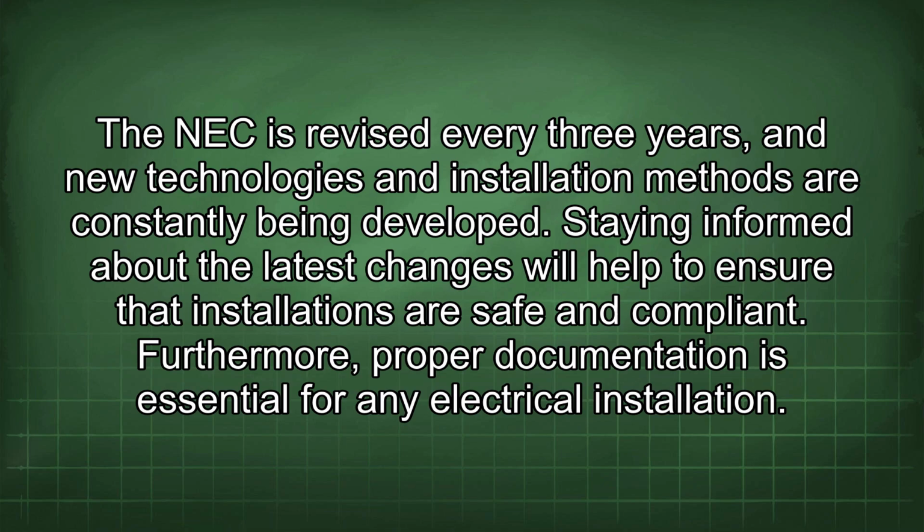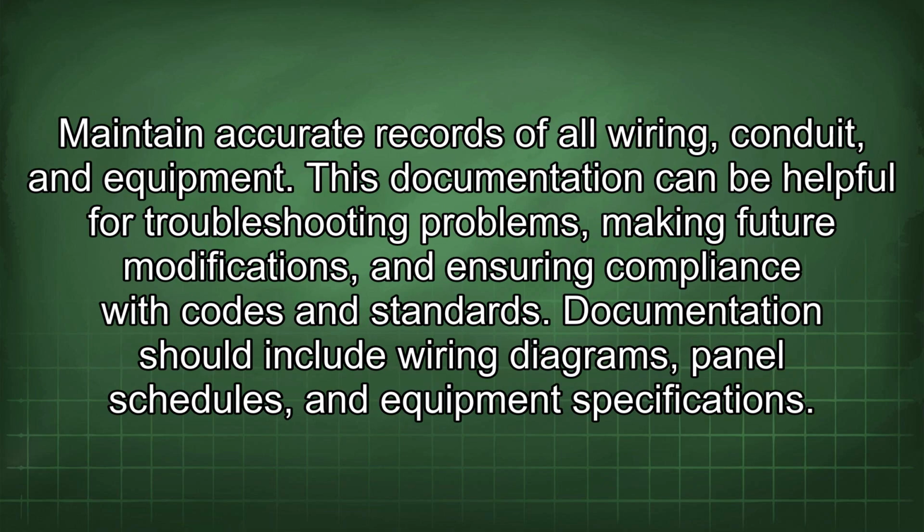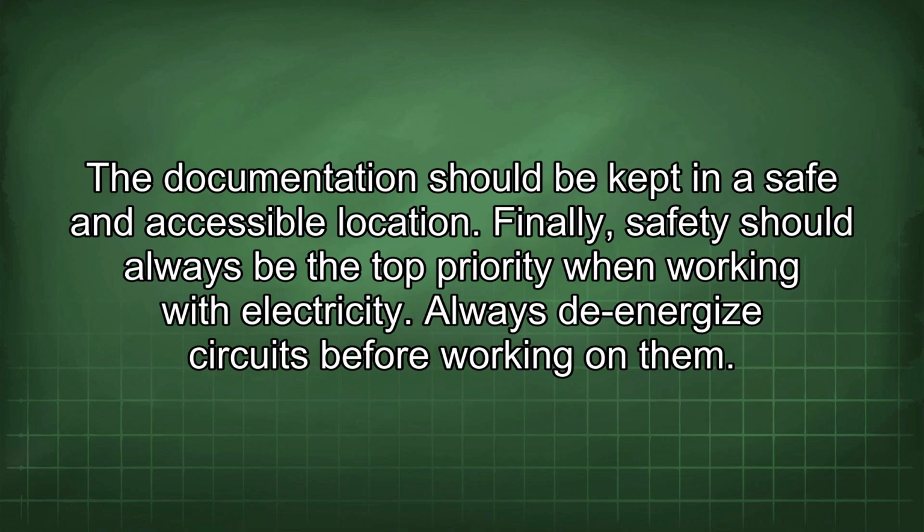Furthermore, proper documentation is essential for any electrical installation. Maintain accurate records of all wiring, conduit, and equipment. This documentation can be helpful for troubleshooting problems, making future modifications, and ensuring compliance with codes and standards. Documentation should include wiring diagrams, panel schedules, and equipment specifications. The documentation should be kept in a safe and accessible location.